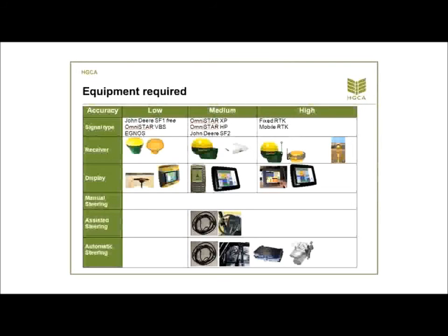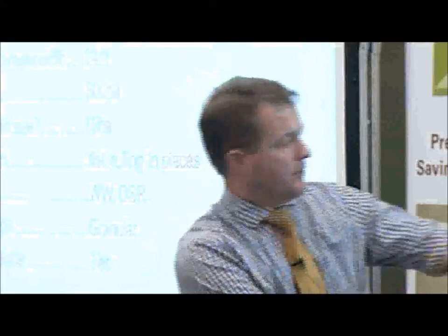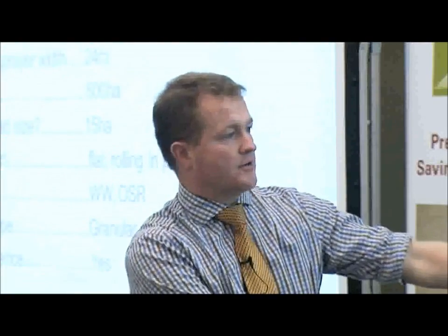And then to actually make the steering work, if you've got an older machine that's not equipped with all the components that the modern machines are, you'll need some component that allows steering to take place. You can have digital motors that strap onto the steering column and harnesses. And then on more modern machines, you have it all incorporated. So you have the electric valves, the harnesses, and the sensors needed to make it all operational. On this one, do I have to have it on a new tractor? Do I have to buy a new tractor, or can it be retrofitted? No, it can be retrofitted. It depends a little bit on the age, serial numbers and things like that, but a lot of this technology now will retrofit on older machines, yeah.